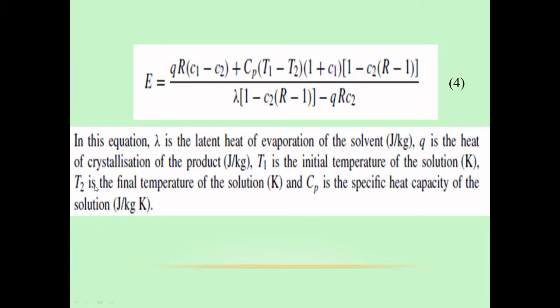If the amount of water evaporated is not given, you can solve for it in terms of ratio of it with the initial water in your feed to the crystallizer. However, all of this information that I have just read should be available. If not, class, it's okay to assume that there is no evaporation. That, of course, is a simple process of cooling to facilitate the growth of crystals.